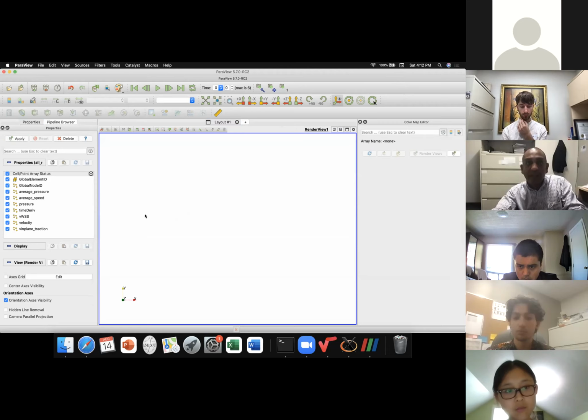And as soon as you've pressed OK, especially in case of SimVascular outputs, not in case of Chaste, not in case of VCPL, but in case of SimVascular, SimVascular is organized in such a way that as soon as it writes some output, it chooses to write everything it knows unless you tell it not to write specific things, okay? And so in this case, it looks like the simulation chose that everything should be written. So what is accessible to SimVascular? Let's take stock of what is accessible to SimVascular when it chooses to write VTK files, okay?